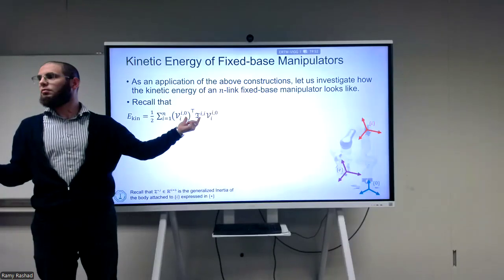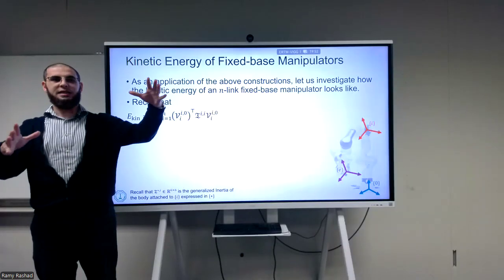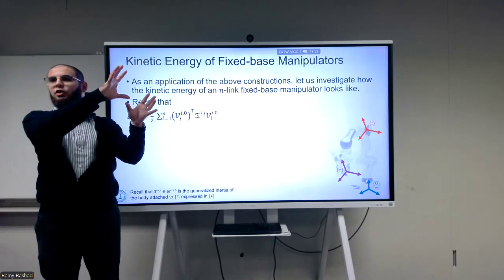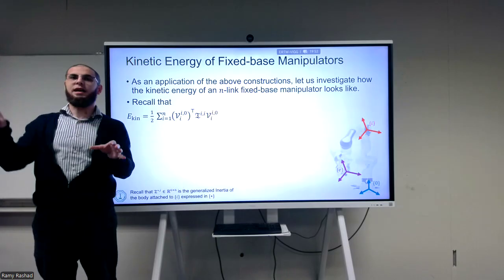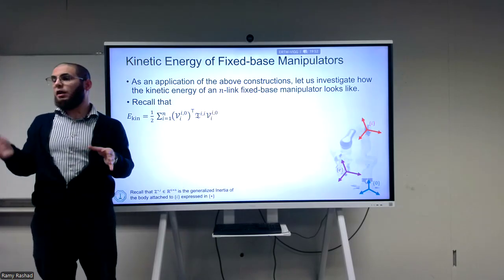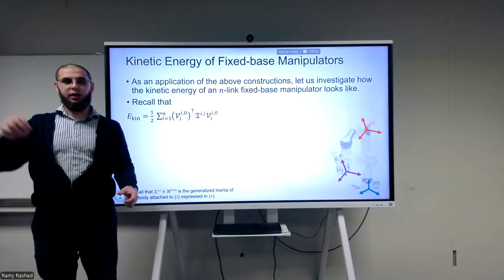It becomes just a constant matrix, a constant 6 by 6 matrix. It had J on the top, it had mass multiplied by the identity, and on the off-diagonal terms there was the tilde form, the skew symmetric matrix, of the center of mass location.